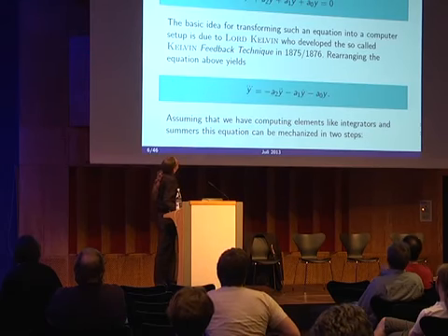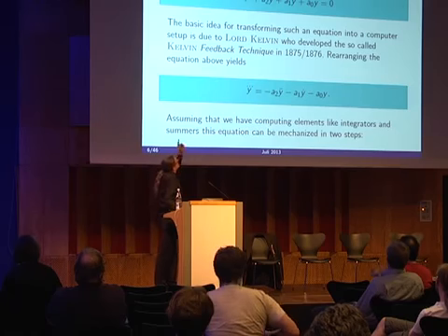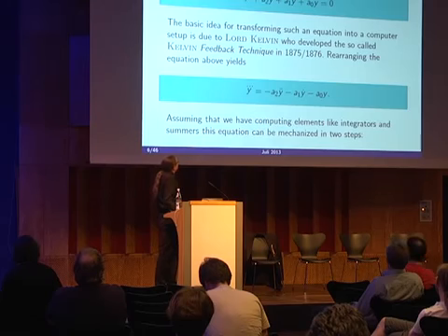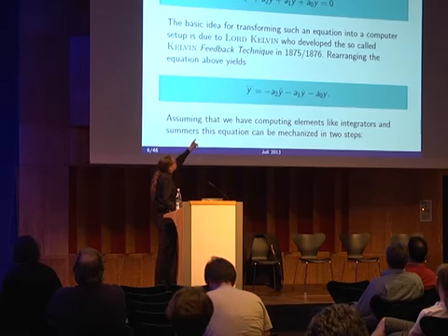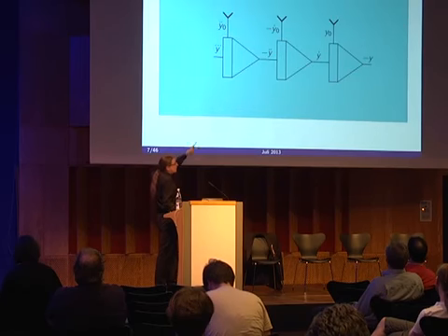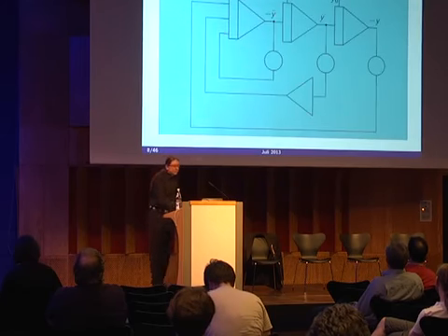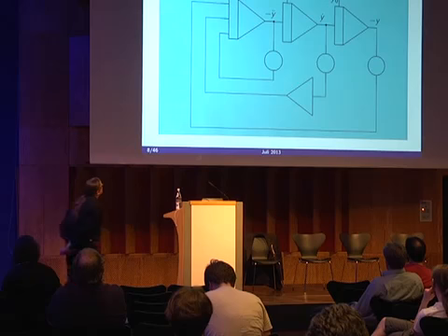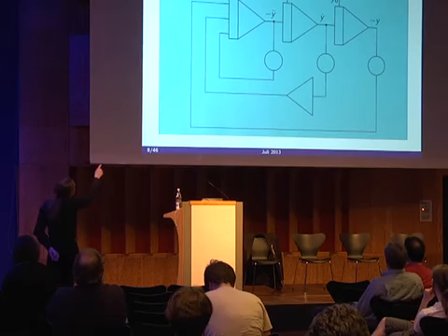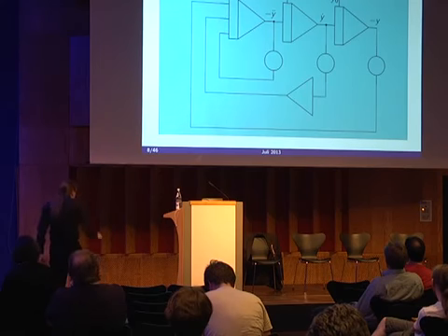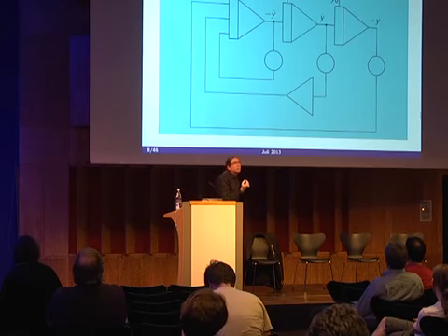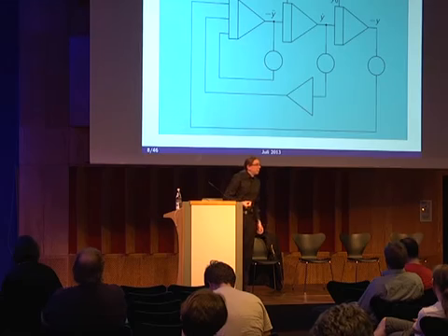And you see, these variables are summed with some coefficients to yield a value like 0, or if you look at the second form of the equation, to yield the value y dot dot dot. So if I take this subcircuit and introduce some feedback paths, I can yield the highest derivative, which I was looking for in the first place, by adding minus y dot dot and minus y dot and minus y to yield eventually the y dot dot dot that I was looking for. And what is this? This is a program. That's a program for an analog computer.